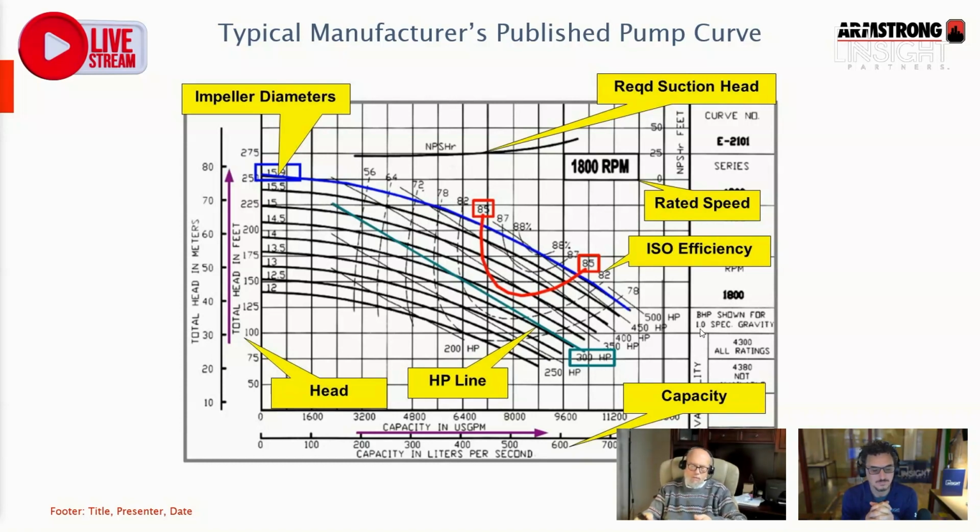If you look at a pump curve or a fan curve, we may require a 450 horsepower motor, but the absorbed power, the brake horsepower, may only be 400 horsepower. So what we show is that combination of the two for hydraulic efficiency and absorbed power efficiency, because that's how we have to rate pumps based on HI and DOE and everybody else.